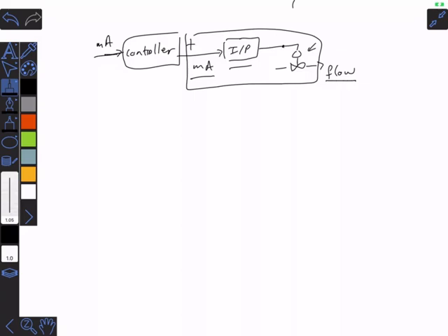And if you actually want to calculate the numeric value of the gain correctly so that all these intermediate signals fall within the correct values, if you want to simulate everything and you want to know what the pressure signal to the valve is and what the milliamp signal would be, then you have to do this calculation that way. But in most cases, we are only really interested in that zoomed out layer. But it is important to ask yourself where we are focusing.